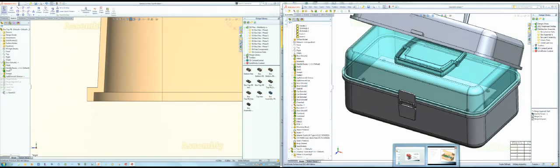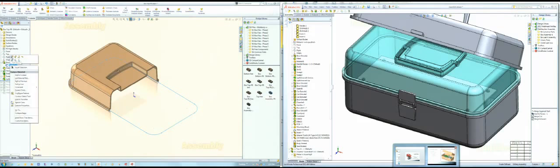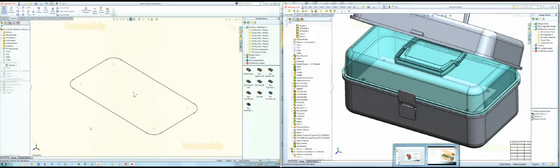The other thing we can do in here, where's the problem? This boss feature here. The original sketch, get out of this sketch first, and the tools you use all the time here. You know, what's the relationships on this? They're all on-edge relationships. So I could go into the sketch, display, delete relationships. If you go in here, you can choose, say, just defined in context. Delete them all. Now what do I do?